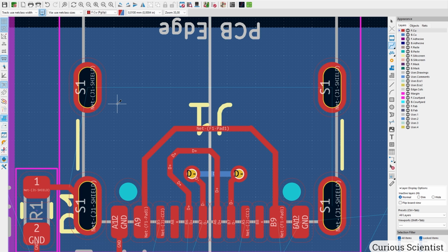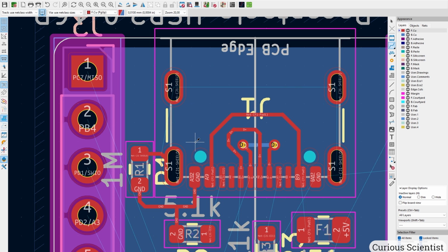It will throw an error or a warning when we do the electrical rules checking, but we can neglect those violations or alerts because it's not a real error. So we can put them on an exception list. But you can see that, yeah, this wants to be routed together, but you don't need to route it because it's already routed due to the nature of the part.